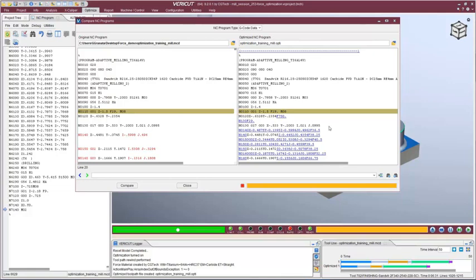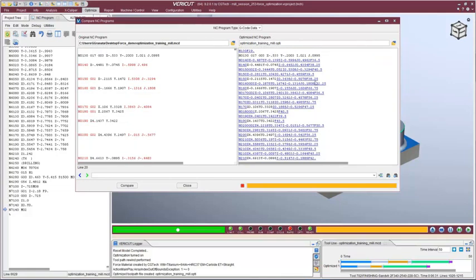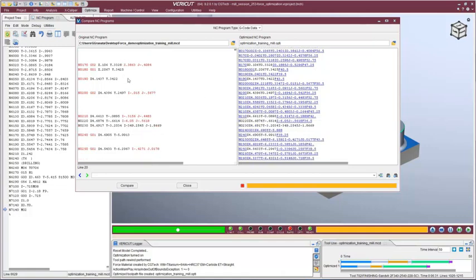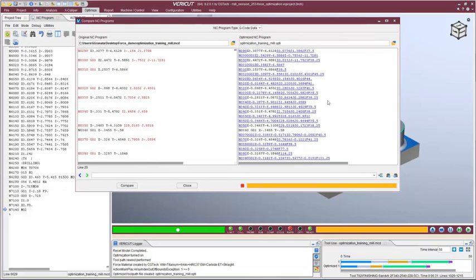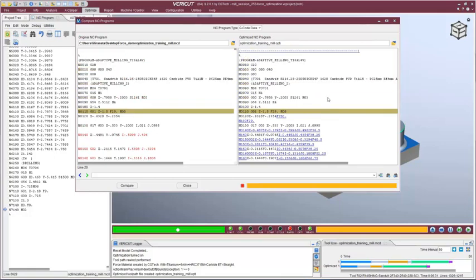But after that, look what happens with all of the feed rate scheduling that goes on and block breakup. This is the amount of subdivision that causes very precise, constant chip thickness at the ideal thickness you want for machining this material. Nothing like the program that came out of the CAM system. So that's what's causing all of the savings.